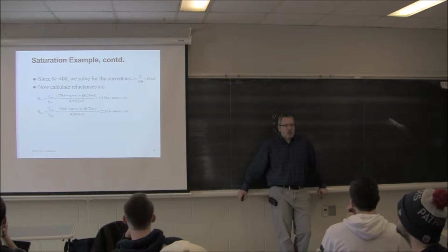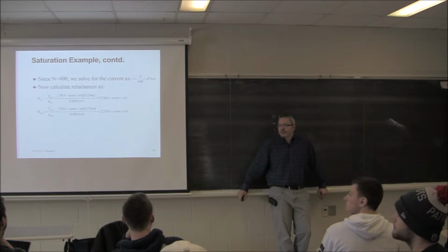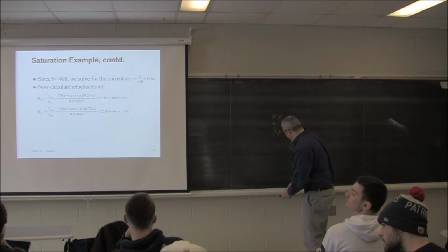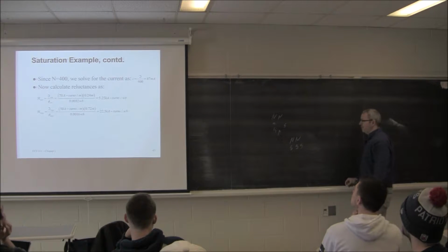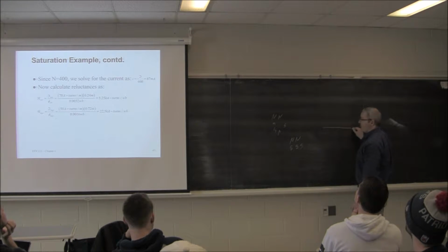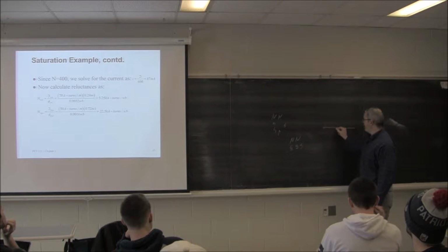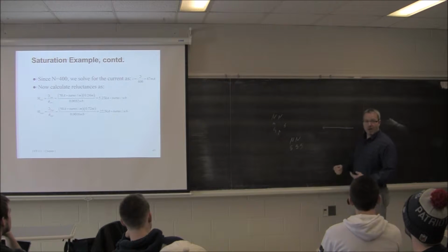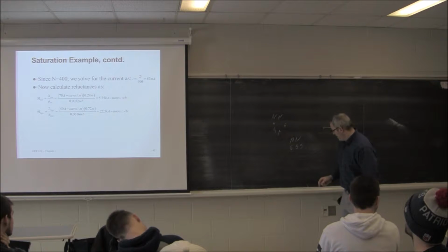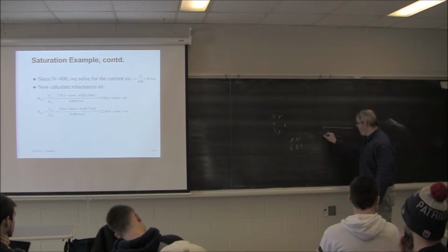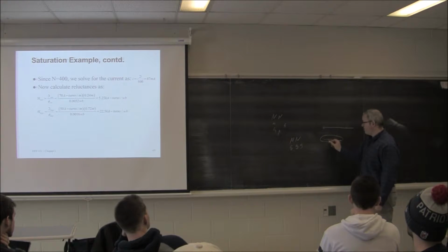Most of the time you see more turns because magnet wire is cheap. Anybody know what magnet wire is? I don't know. We used it on a project for PLCs last semester. When you run a current through it, it allows a pretty impressive magnetic field. Well, sort of. The only difference between magnet wire and regular wire is the insulation. Magnet wire is designed to be run on top of each other. I could not run two regular wires touching each other, because why would the current run all the way around that leg when it could just bypass it?